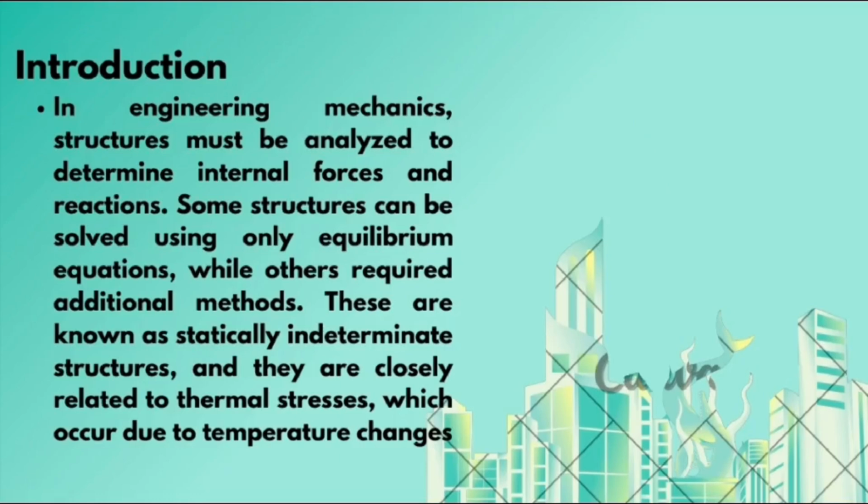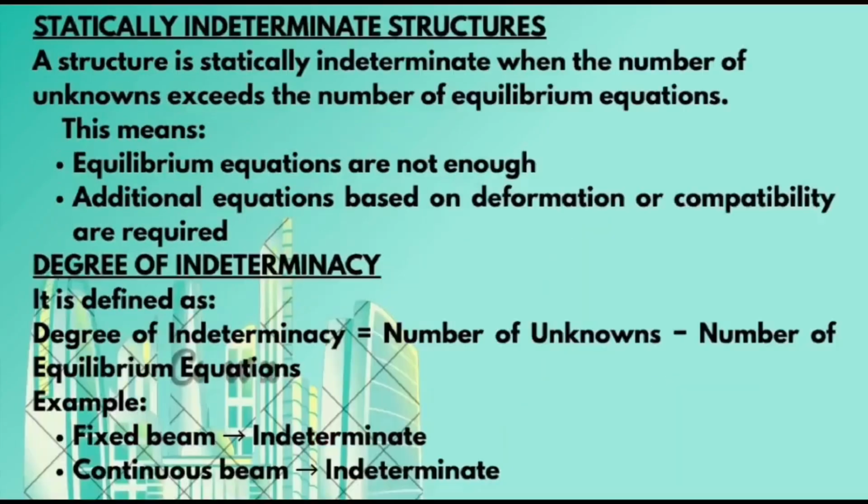In engineering mechanics, structures must be analyzed to determine their internal forces and reactions. Some structures can be resolved using only equilibrium equations, while others require additional methods. These are known as statically indeterminate structures, and they are closely related to thermal stresses, which occur due to temperature changes. A structure is statically indeterminate when the number of unknowns exceeds the number of equilibrium equations. This means equilibrium equations are not enough. Additionally, equations based on deformation or compatibility are required.